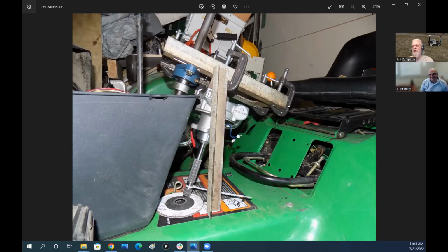And the other thing I was trying to do was, by the time I'm done, I want this blade height adjustment here. So you push down this lever and you can run this handle up and down. So I still want that to be able to get full travel. So I have to be careful hitting things up here. And right now with the seat on, if I fold the seat forward, this was too long. So I actually end up cutting part of this off this frame here, and then the seat will come forward and not be a problem.